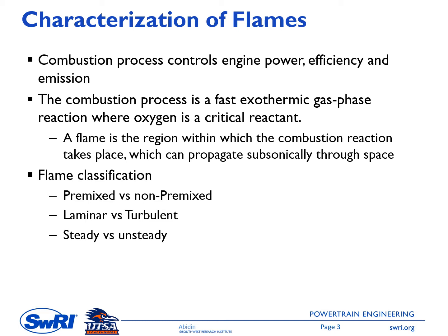We might also have a self-auto-ignition ahead of the flame front, and this auto-ignition can generate engine knock, which, due to the high pressure generated, can lead to engine damage.